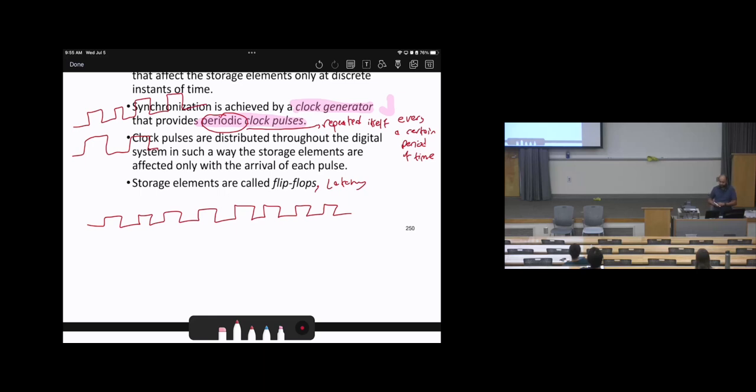As we know, the logic gates are based on transistors, like NAND gates, NOR gates, and NOT gates. So we have three types. Then we can create AND and OR from all of these three gates, as we know earlier. All of this is based on CMOS, or NMOS and PMOS transistors. So from these transistors we can create the logic gates. Then using these logic gates, we can create latches and flip-flops.